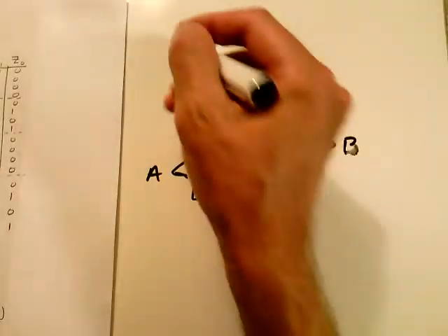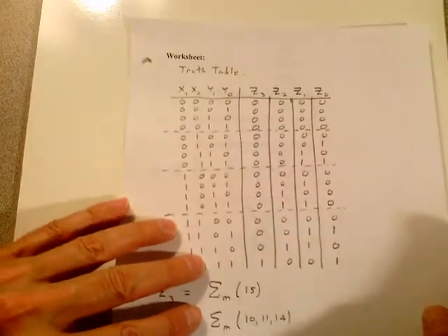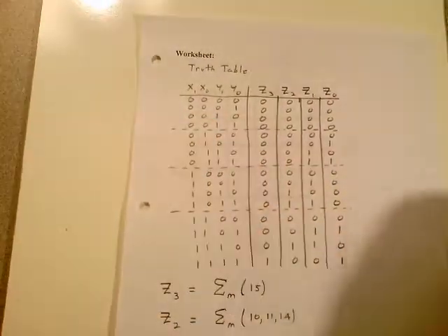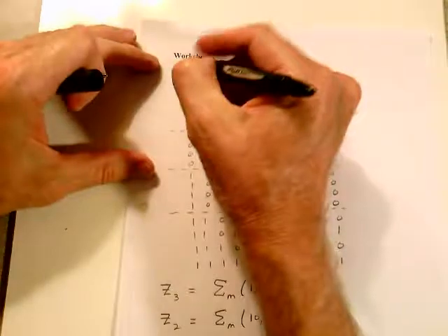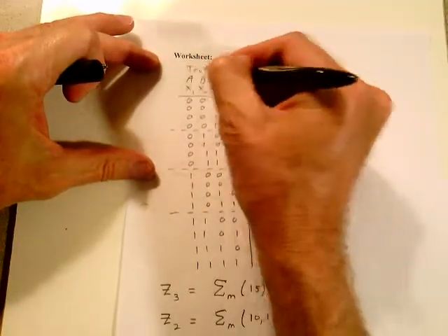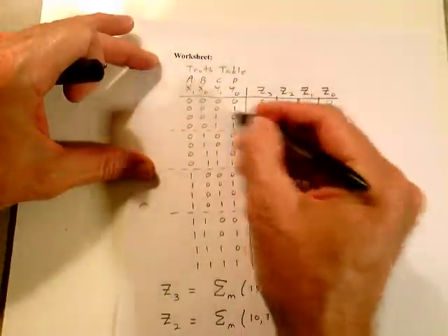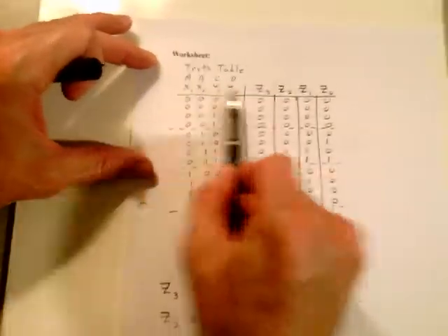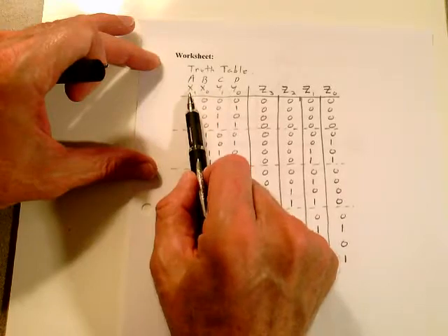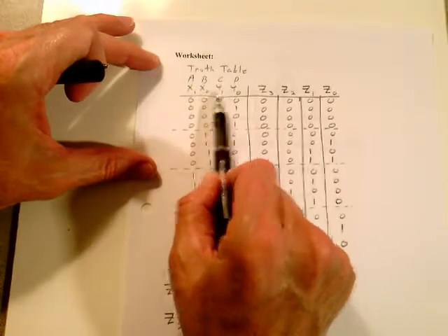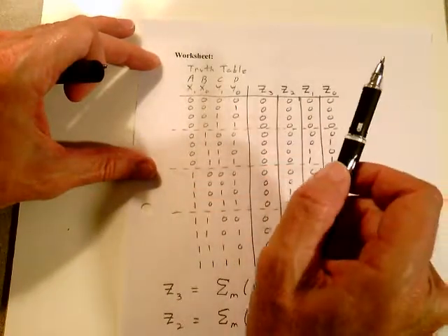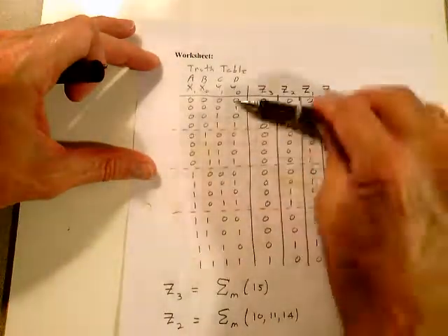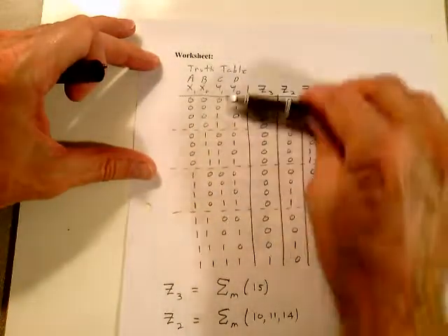But if you look at the top of our truth table here, this would have been your A, B, C, D. I don't care how you lay this out up here. Just lay it out the way, you know, the Y1, Y0, X1, X0 could be in that order. Then do your sequence 0 through 15 and count as you go so you don't miss any.